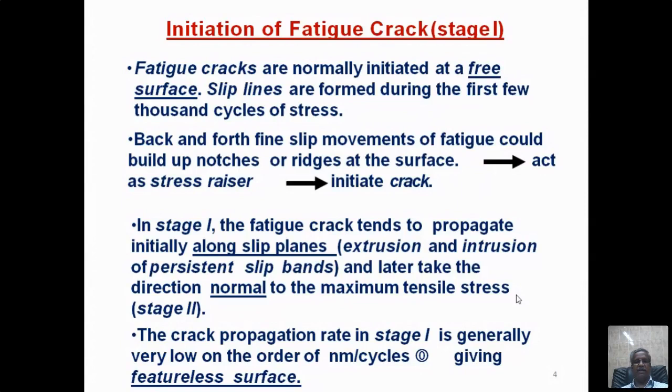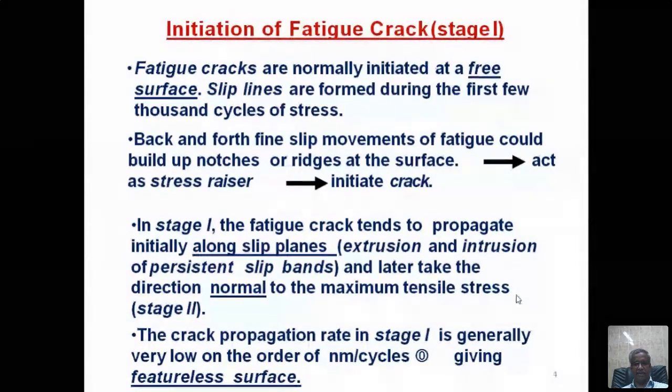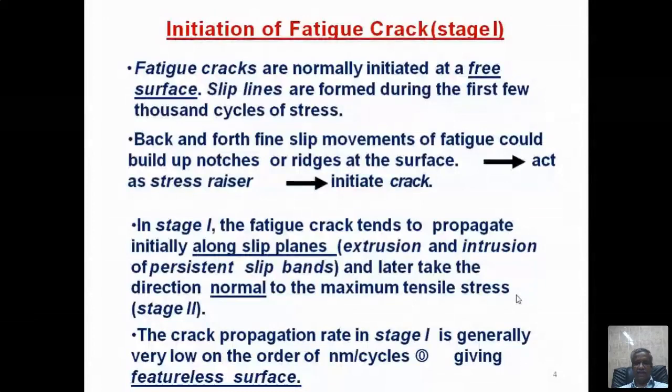Then those notches and ridges will act as stress risers, and once they act as stress risers, the crack will initiate from that location. We'll see how it happens in the next slide.